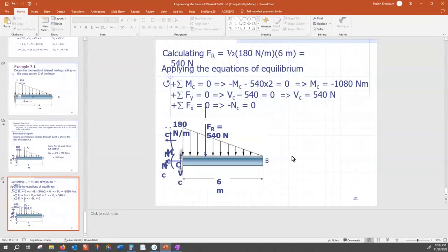In the general case, there are 3 internal forces. Axial, responsible for making the beam longer or shorter. Shearing internal force, which does a scissor effect. And the bending moment, responsible for changing the radius of curvature.